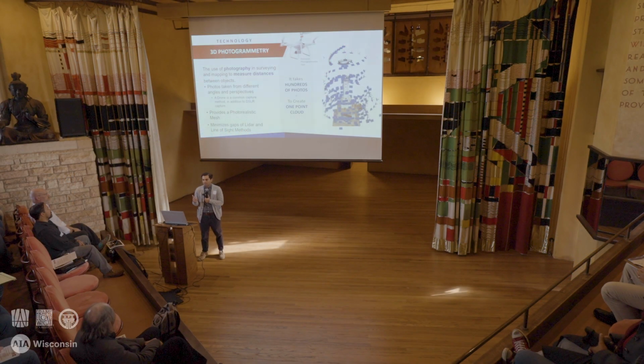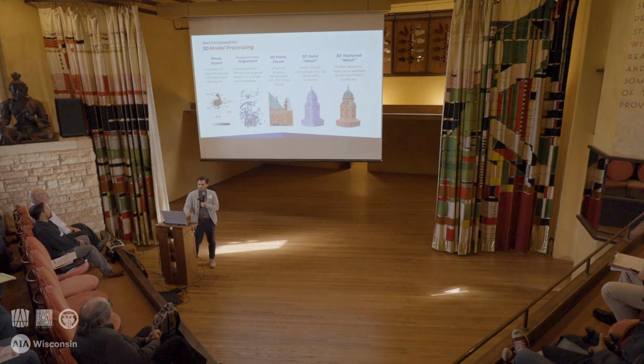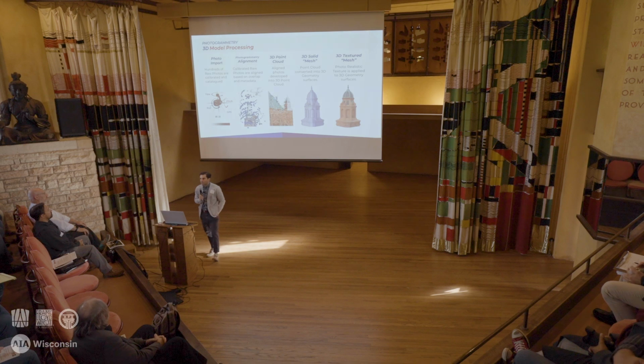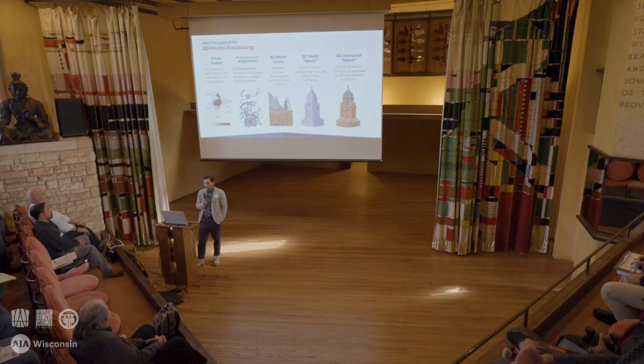The metadata is embedded in each of the images, so you're recording the different pitch and roll, the generic GPS location, or if you have a drone that has the survey capabilities on it, a more precise survey GPS location. But all that metadata allows you to then tie the images together to get you a 3D textured mesh or a point cloud.